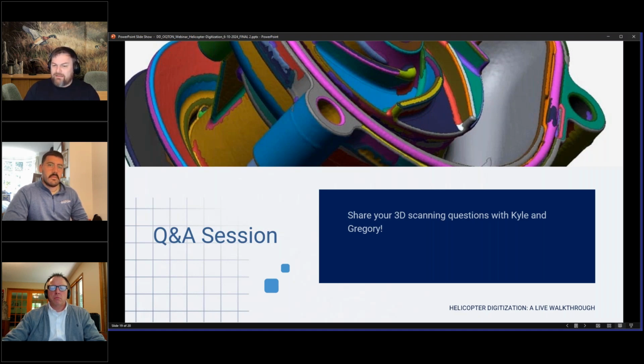And my software has the ability to fit exactly to it, so it would fit and average out and create that 2.97, whatever. And then DX also has the ability to add the design intent. So once I fit that circle, I could then override it and make it 3 inches and infer that it must have been a 3-inch circle. So there has to be at least a little bit of knowledge of understanding what you're trying to create and what the tolerances are based on the size and scale, purpose, and the materials involved. And again, that's the engineering side. Our software does have that ability to round and average and all those other things. But one of the things Design X is giving you is the ability to either fit things as existing condition, just like they come from the scanner, or actually fit them and override them as what we call design intent.